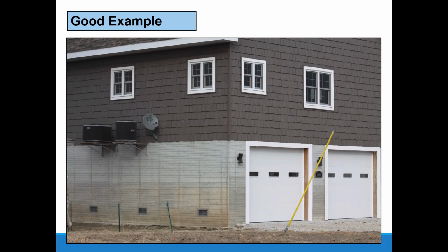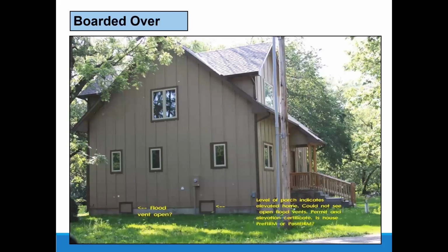And there was a flood in this area. You can see the high water line on the enclosure, and you can see the flood openings along that wall. This is just a garage floor, and they were able to recover after a little bit of light cleaning. And that was it. They were fine, and that structure was inundated for like 2 months. So they were displaced for a long time, but the structure did not suffer any damage. So built in compliance, used as it was supposed to be, the utilities were elevated, and there was no damage to that structure.